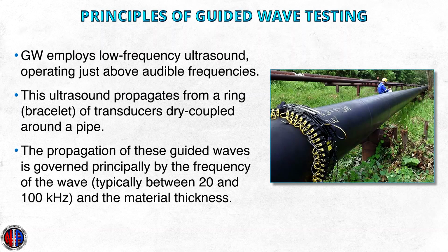Principles of guided wave testing. Guided wave testing employs low-frequency ultrasound operating just above audible frequencies, propagated from a ring of transducers which are dry-coupled around the pipe. The propagation of these guided waves is governed principally by the frequency of the wave and the material thickness.